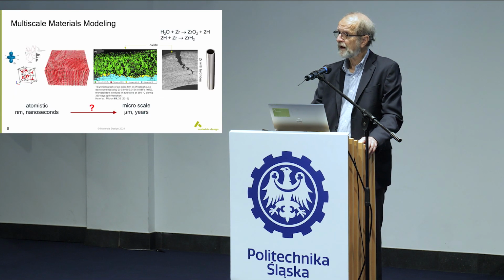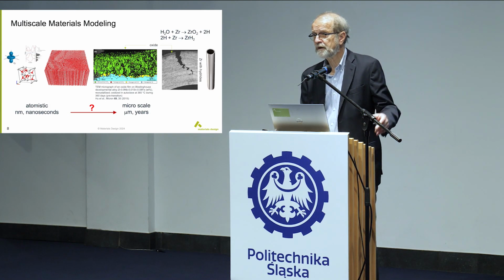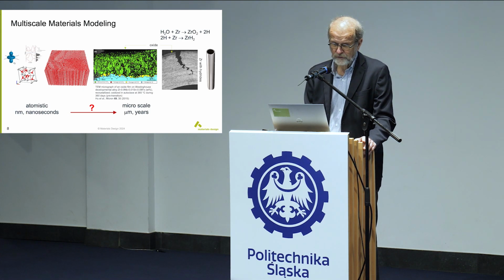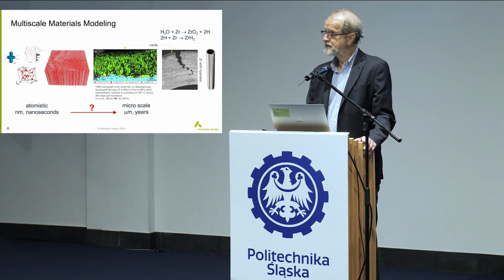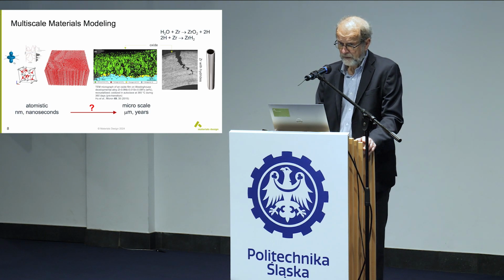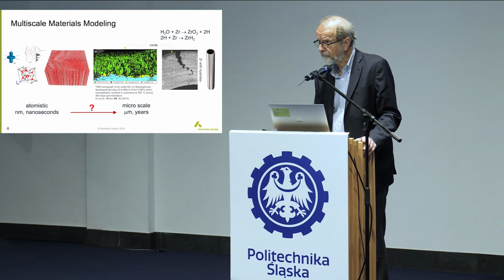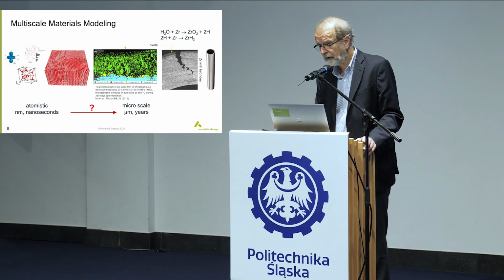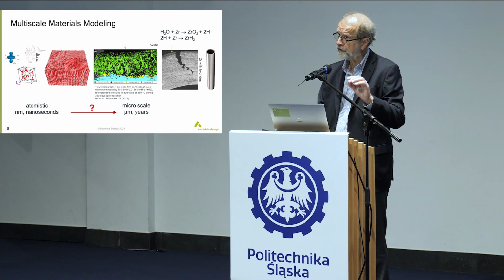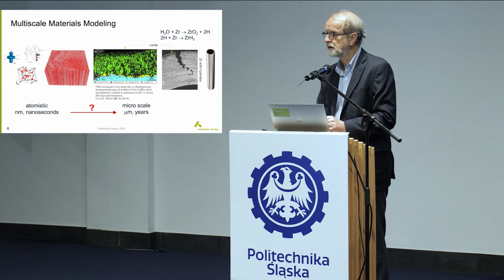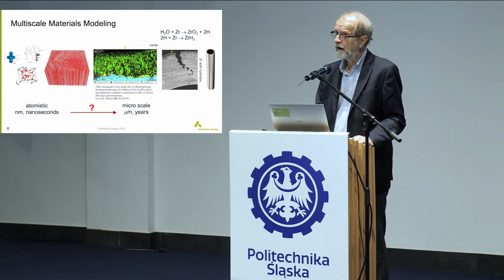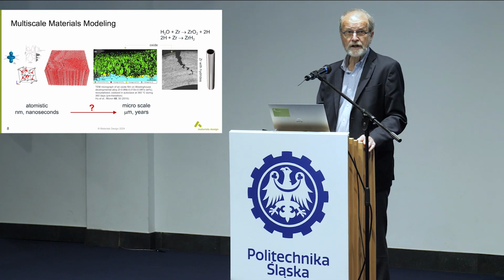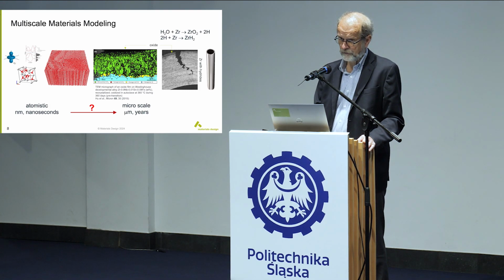So here we are again. You're talking about a time of the fuel bundle of maybe 18 months, maybe 2 years, maybe even longer. And on the atomistic scale, now we're down to nanoseconds. So how do we connect that? Well, we need several layers. So let's set as our goal that we want to predict the microstructure evolution of the oxide film that is building up here. Because if we can reduce the oxidation rate, we reduce the production of hydrides, and we win all along. So what is the oxidation process and how does this microstructure come about? And that's actually a TEM image from the group of Chris Grovenor in Oxford.